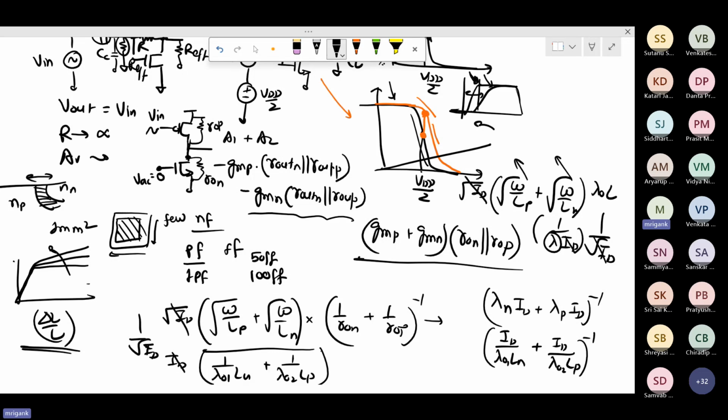And second is, if you look at the Ln and LP. If you increase the Ln and LP, as well as if you increase W of L and W of P, you will get bigger gain, right? So that means here W has to be increased. Here Ln and LP are under root, here it is outside root. Increasing the Ln LP will also improve the gain.